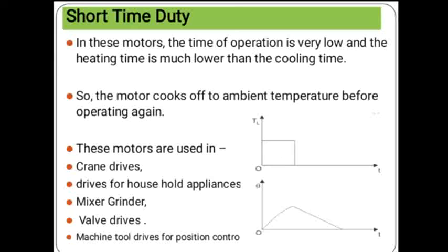The heating time is much lower than the cooling time. We can also say that in this type of duty, the time of drive operation is considerably less than the heating time constant, and the machine is allowed to cool off to ambient temperature before the motor is required to operate again.